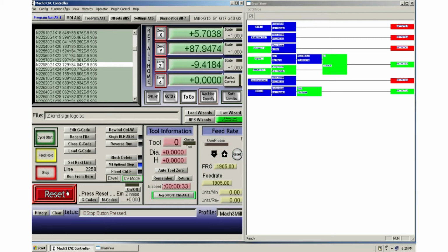Finally, if I click on the reset, the brain is not taken into account, but the machine goes into an emergency condition where Mach 3 shuts all outputs off, then the external inverter and the timer take over, making the E-Stop LED flash approximately every 0.33 seconds. As you can see, clicking on the virtual button does not affect the brain at all.